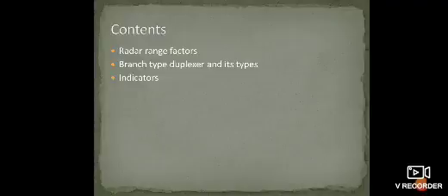The function of the duplexer is that it is mainly used as a switch, controlling the transmitter section and the receiver section, and it provides some protection to our receiver section. Whenever we transmit high frequency signals from the transmitter part, they will not enter the receiver section during transmission. So the duplexer has a number of functions.